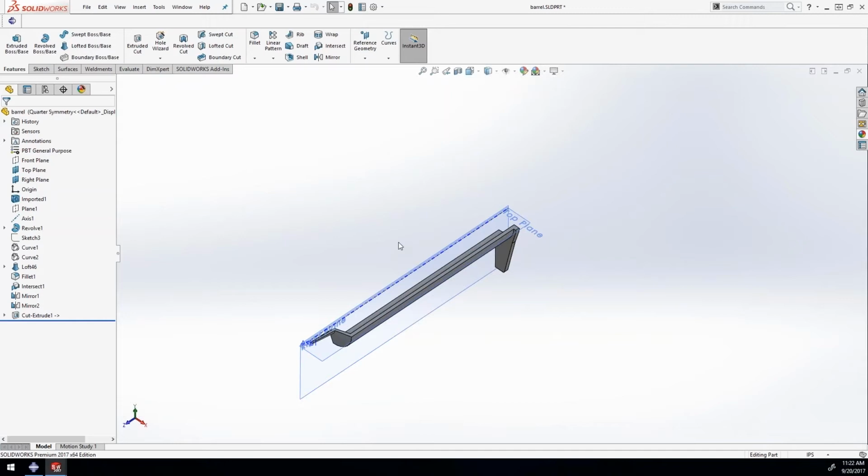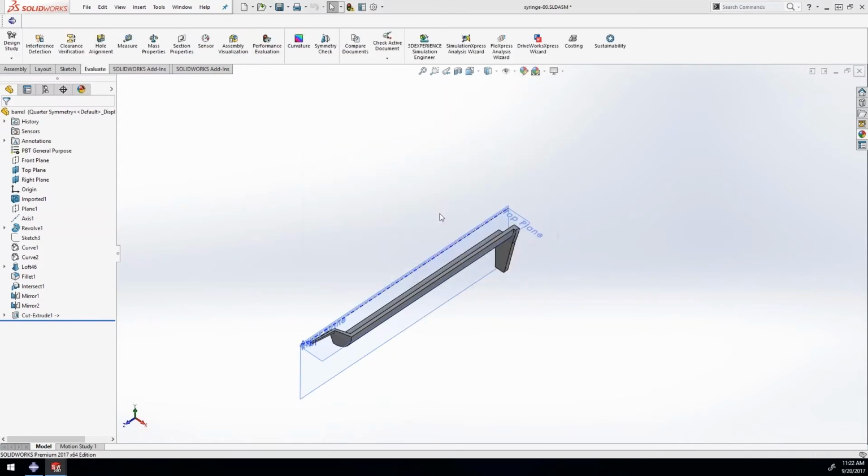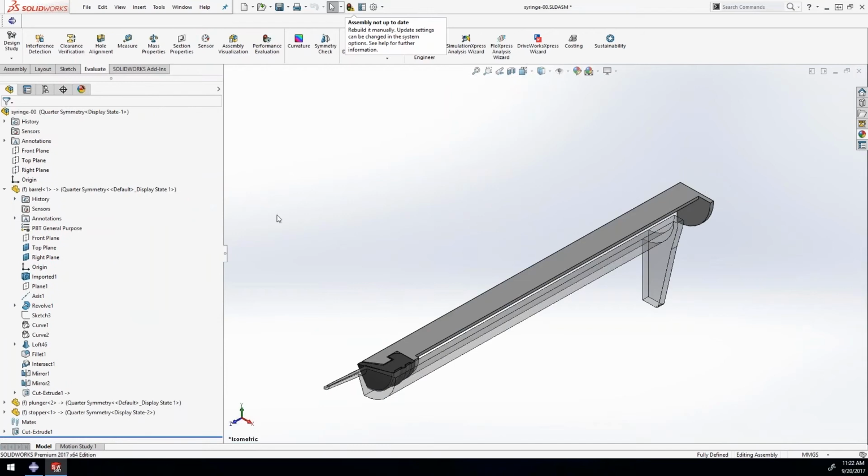And so it's important that your parts are actually saved in the configuration that you want them to be pushed into Abaqus. That also means if you had multiple configurations of a part, you would need to have those parts saved in those appropriate configurations before you do that export. So just something to point out there. Definitely, if you had a lot of bolts with different configurations, it's something you're going to have to consider as you're setting up the configurations. So that's why we have that propagate features to parts option checked on.